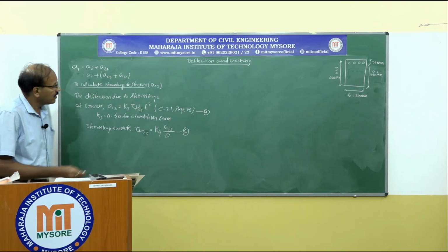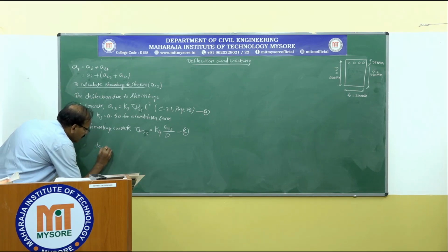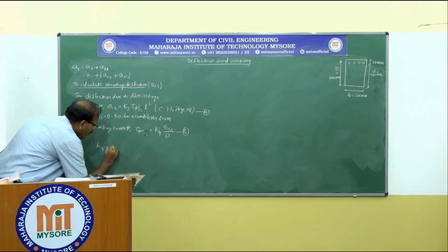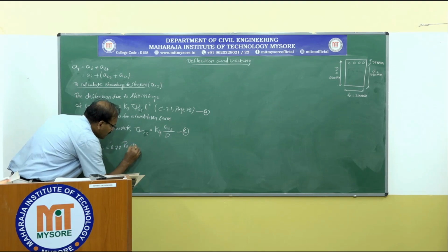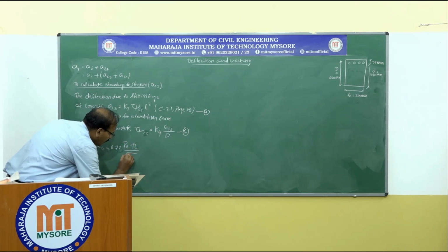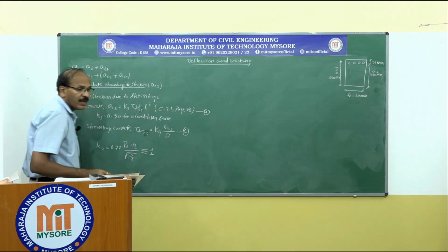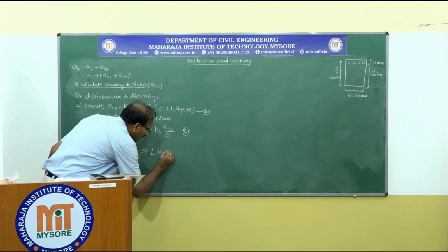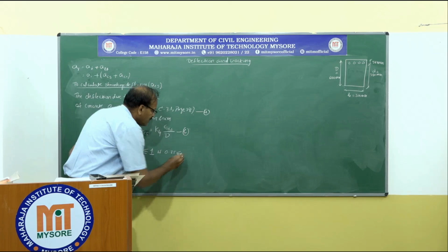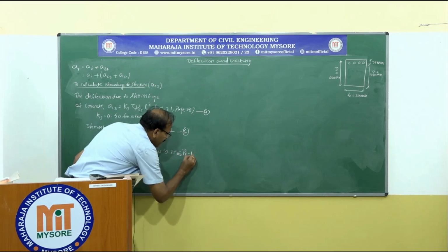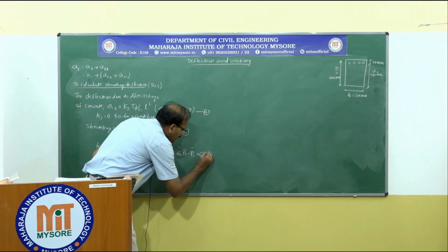As per the code, K4 equal to 0.72 times (PT minus PC) divided by square root of PT, that should be less than or equal to 1, if 0.25 is less than or at most equal to PT minus PC, and that is less than 1.0.